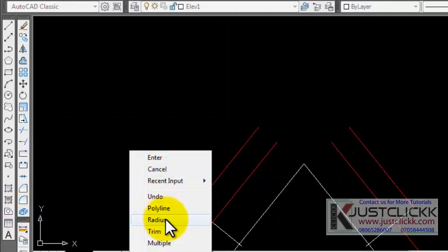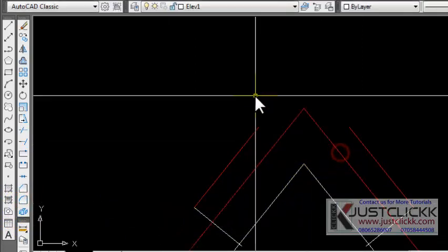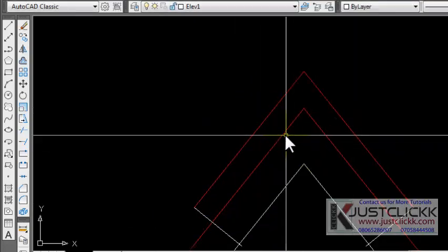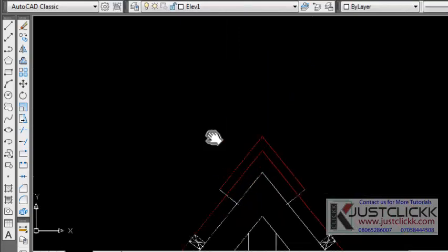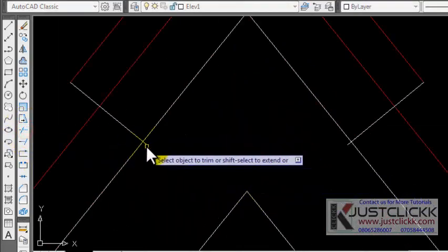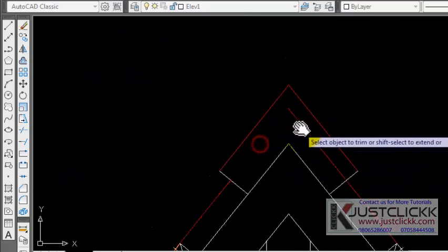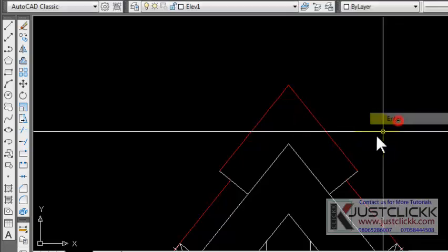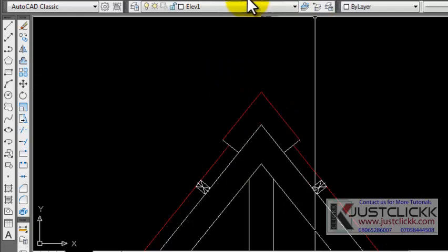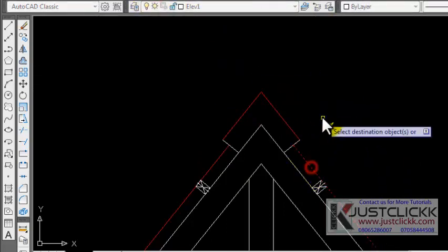Make sure your fillet radius is 0, and then start connecting the two angles, both your roof and the ridge cap. So once you achieve this, you can finally do proper trimming. And okay, you can trim this up. I think that is not supposed to show. You just need to have something like this, and now you can match property.